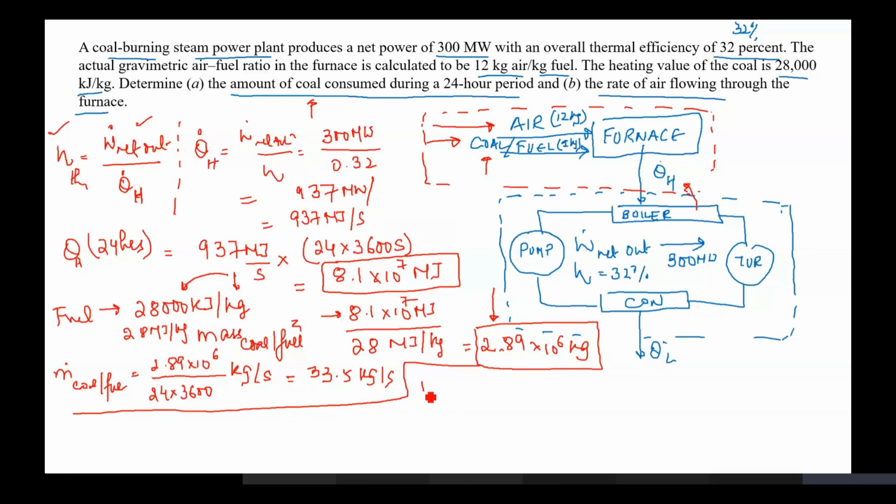All right. So the mass of air to mass of fuel is essentially 12 over 1. Is this clear to you? This means that the mass flow of air would also be 12 is to 1 if you divide both of them per second. Clear enough?